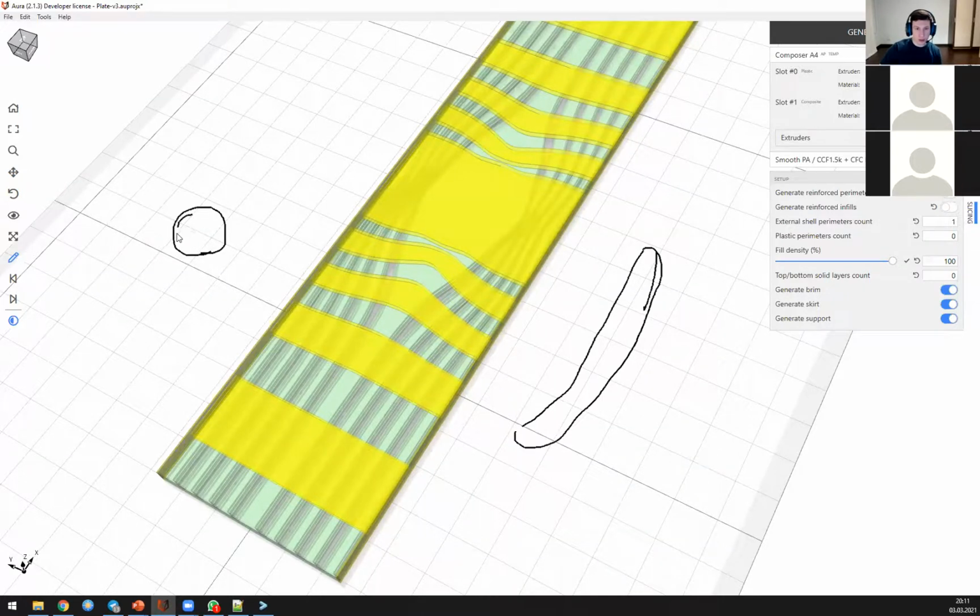But of course, you will have some plastic lines around the wall as well. So maybe around a 5 millimeter hole will be okay to reinforce it with fiber around this hole. And if you reinforce this hole together with the outer contour like this, then there is no such restriction and the hole diameter can be any. Okay, so the next question.